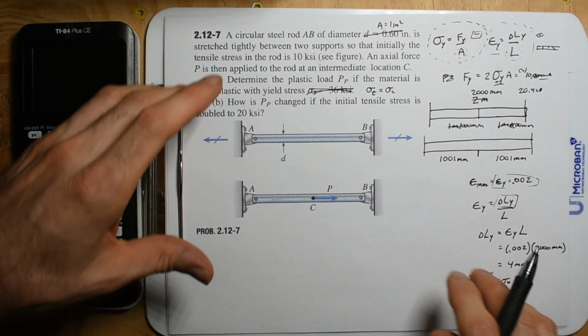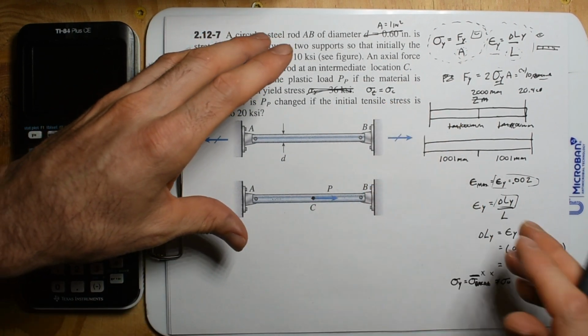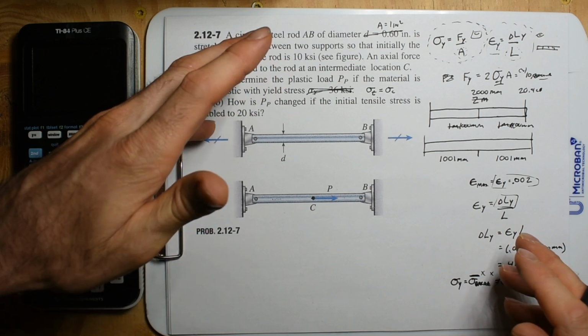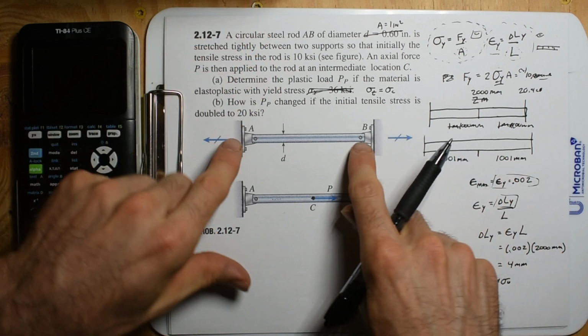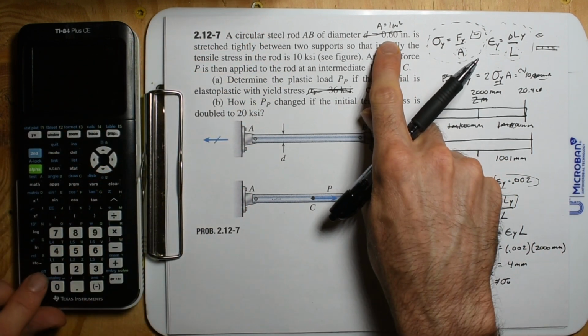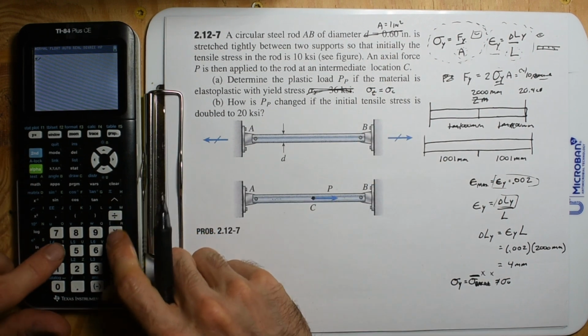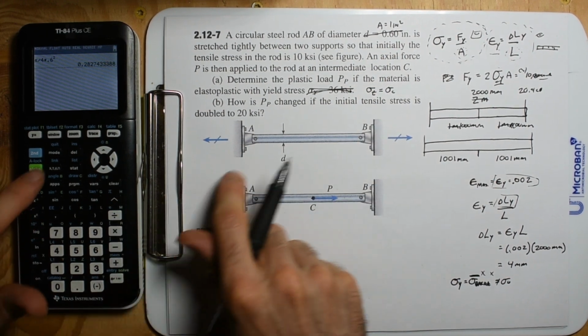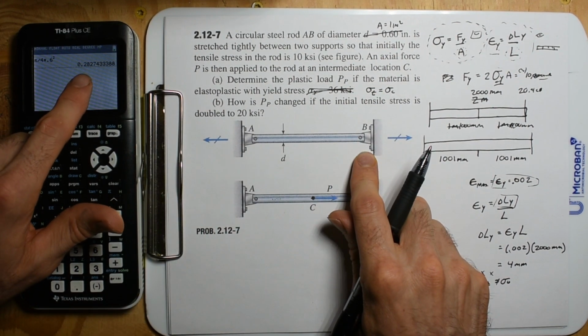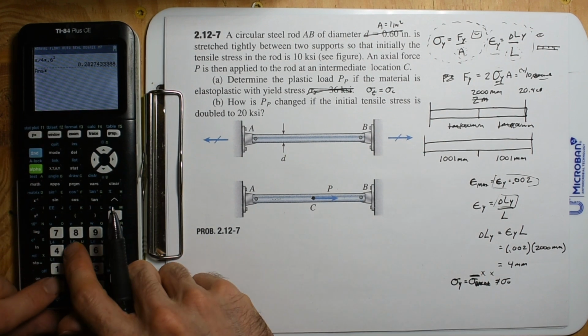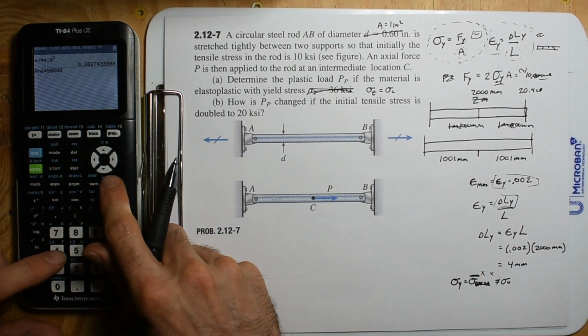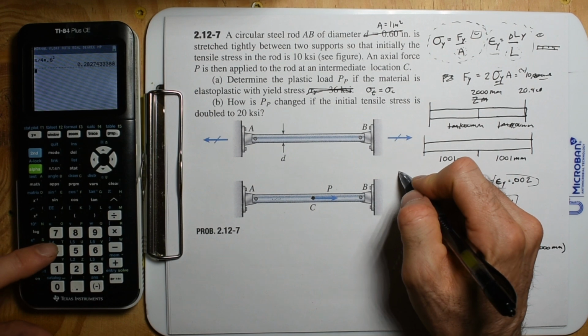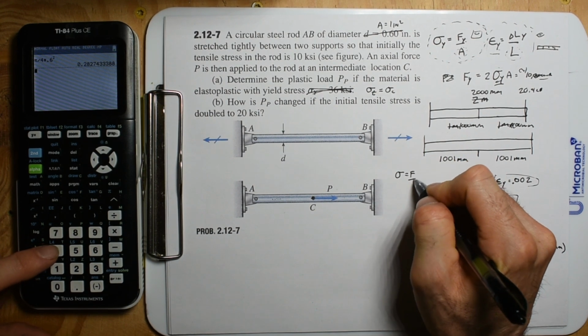So you can easily see if a problem is not ludicrous. Say I have a diameter of 0.6, so I'm going to go pi divided by 4 times 0.6 squared. I have an area of 0.28, so I'm just going to multiply that by 58,000 psi, force over area.